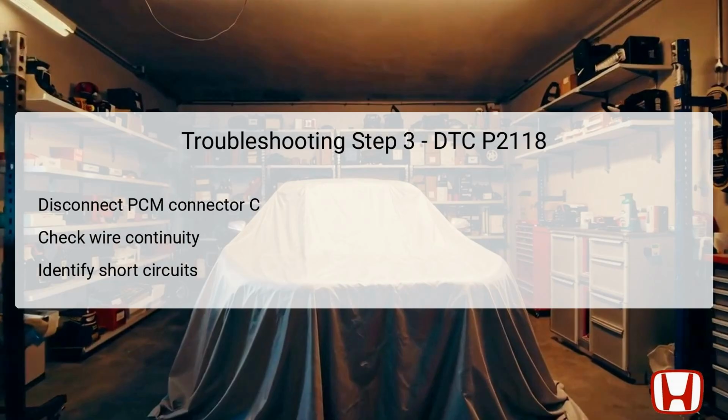These terminals need to be compared to determine if there is any short circuit present between the MTR1 line and the MTR2 line. Should continuity be confirmed between these test points, it indicates that there is a short circuit, necessitating repairs on the wiring running between the PCM and throttle body. If no continuity is observed, the technician will then proceed to step 4 to continue eliminating possible causes of the error.